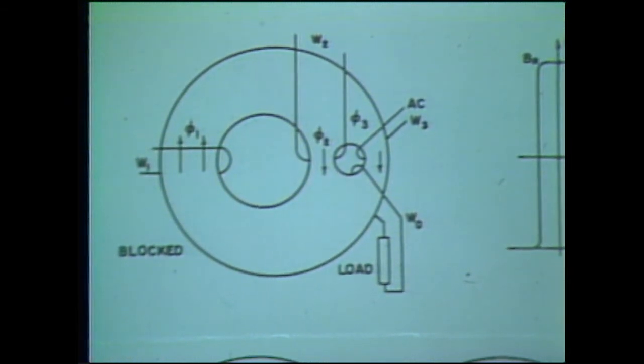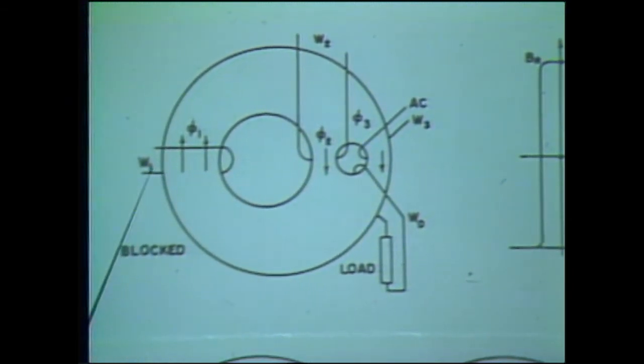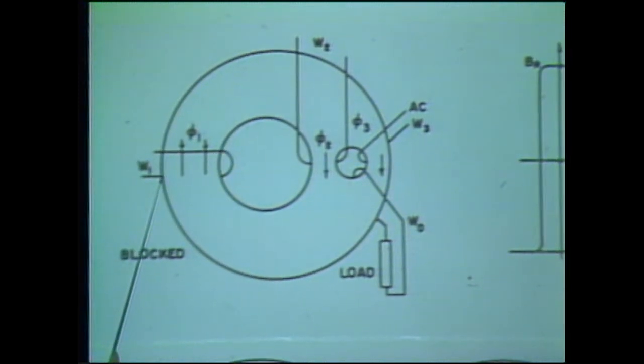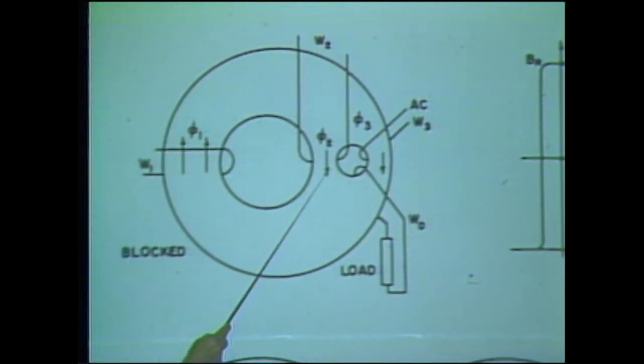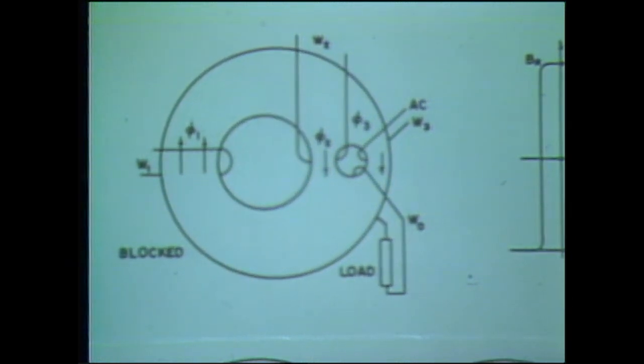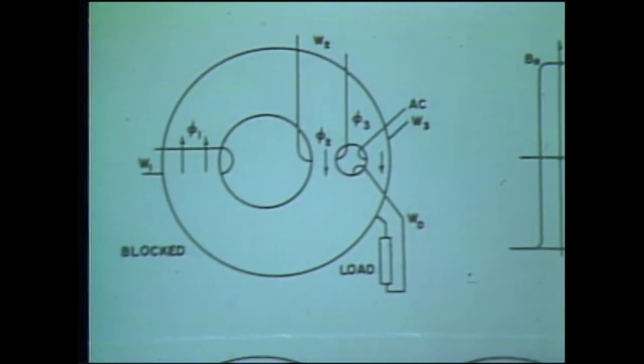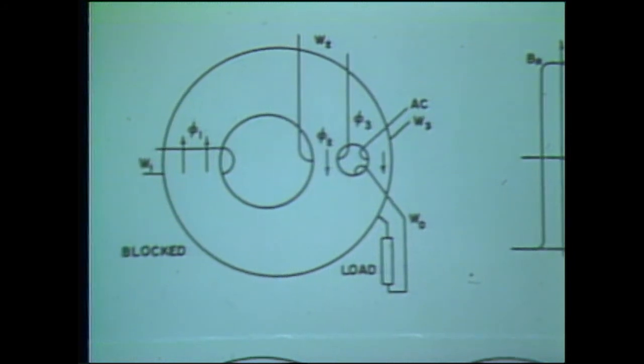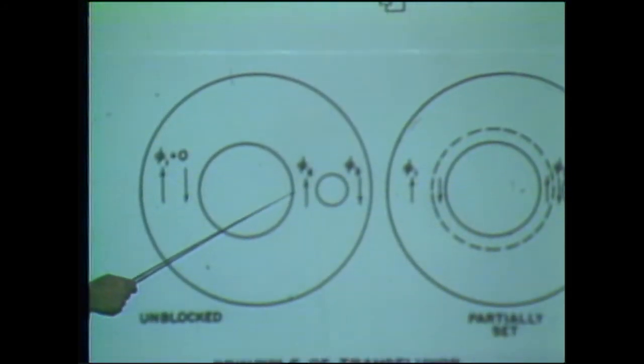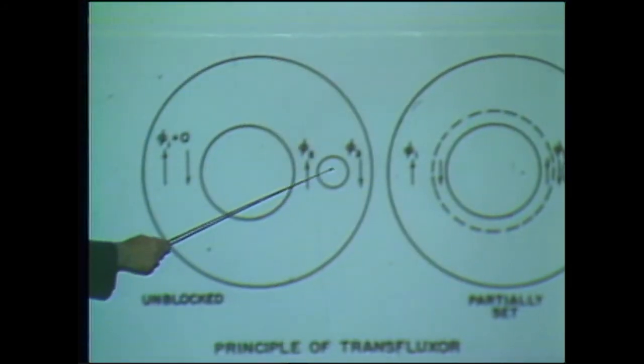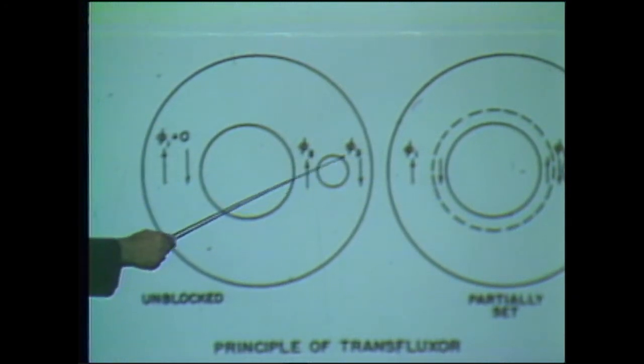On the other hand, if you put a current through this winding that's strong enough to change the magnetization here, but not here, because obviously the magnetization decreases with distance, then you can put the magnetization like this around the two holes, and now if you put AC, it will couple perfectly well.